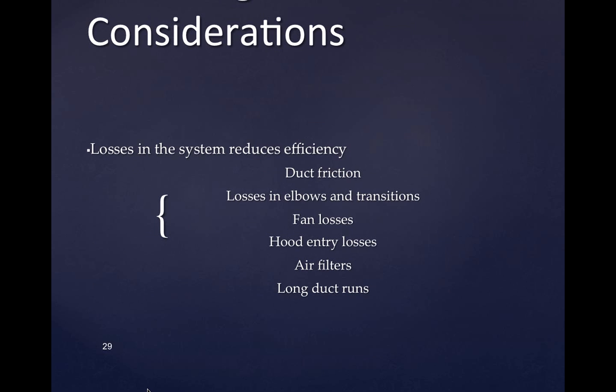Remember what that was? It's a situation where he has exhaust going up and out of the building and then running across a roof. When it comes up the roof and makes that turn, he has a reduction in the size of the ductwork as it goes through the horizontal run. And then when it turns back up, it expands again. Anybody remember why he reduced the size of the ductwork on the roof? He wanted higher velocity. Why did he need higher velocity in that horizontal run?